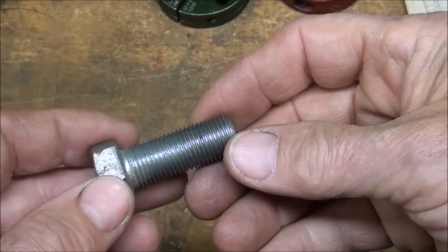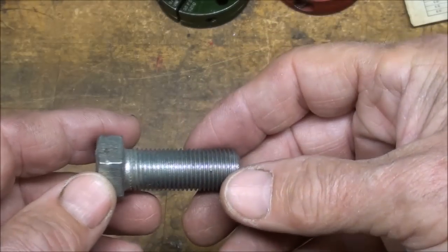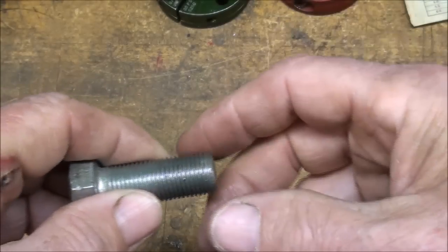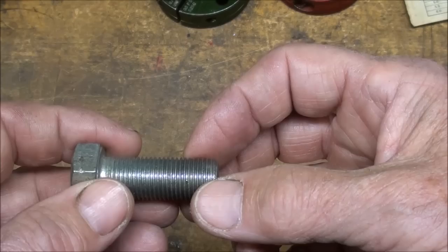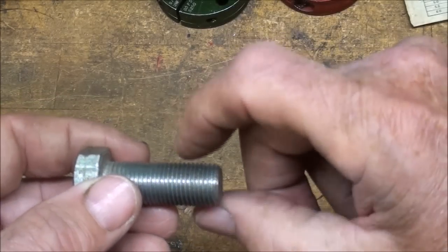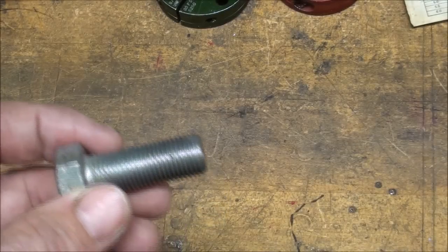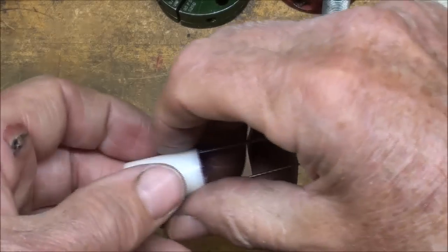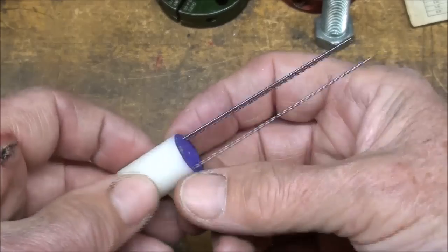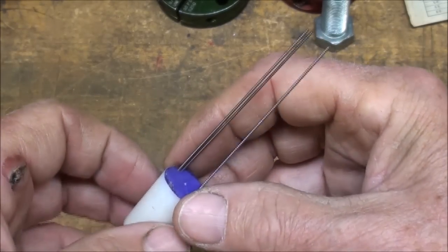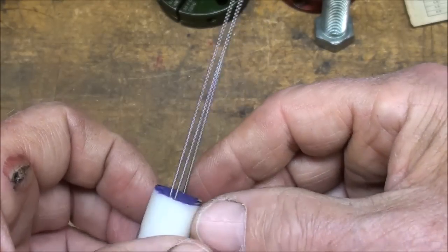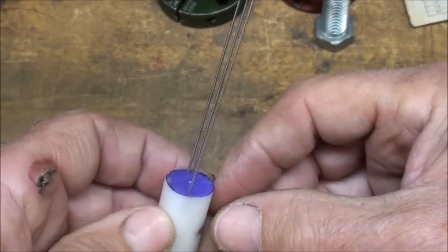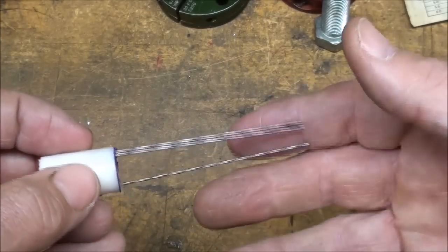Thread wires are difficult to use, and they're difficult because you need 3 hands. Now sometimes this will still be in a machine or in a vise or whatnot, but you still have to hold the 3 wires in place and then a micrometer to measure across the 3 wires. And that can be pretty difficult. So my way of doing that was to take a piece of plastic here, and I used very small drill bits, just a little bit less than the diameter of the wire. I drilled some holes in the appropriate spot, and you can see there's 2 wires on one side and 1 on the other, and that's going to be very easy to hold.